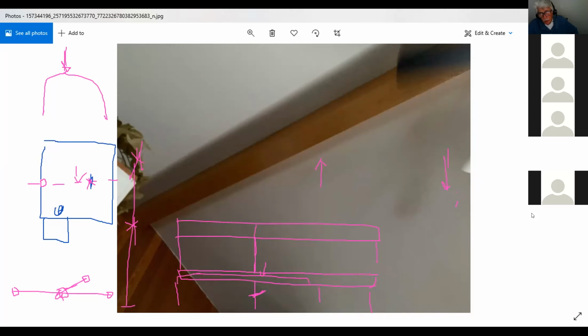So, I mean, everything is doable, but without the information, you can't do anything. And we're not going to second guess it because it has to be done right. So you have to start by looking at the roof. And then from the roof, look at how the loads are coming down. And then after that, look at where the walls are. Are they covering up columns? In other words, did they bury them? Most likely that's what you usually do for aesthetic reasons. You tend to put the columns inside the wall so that they're not apparent, okay?